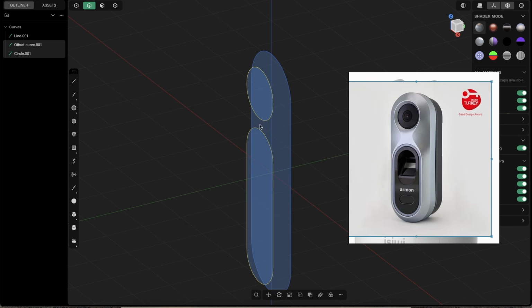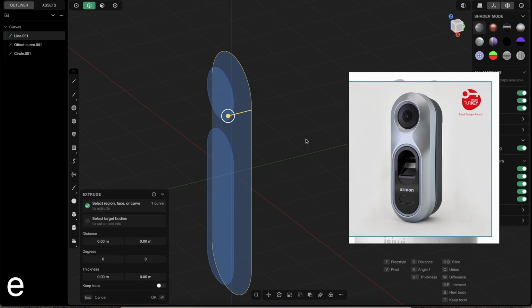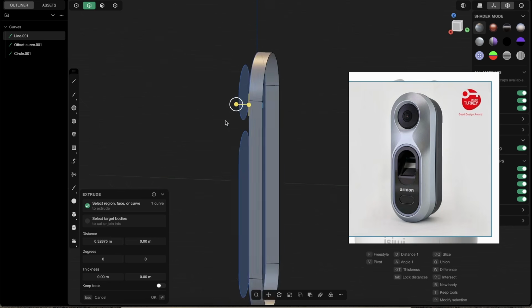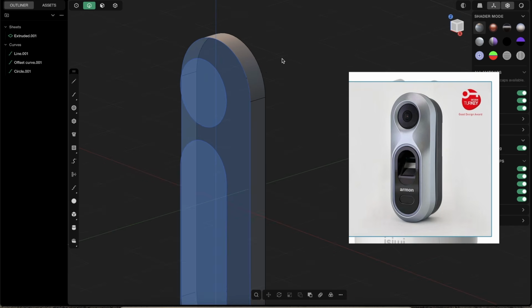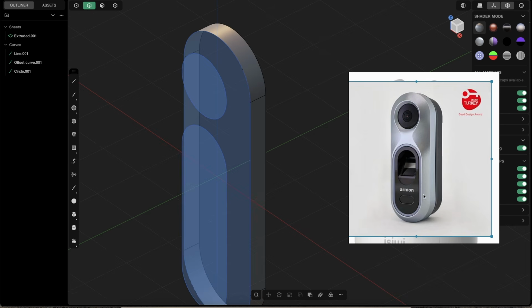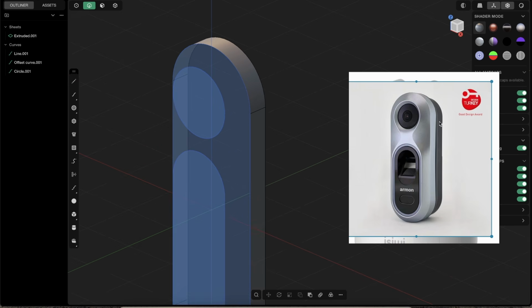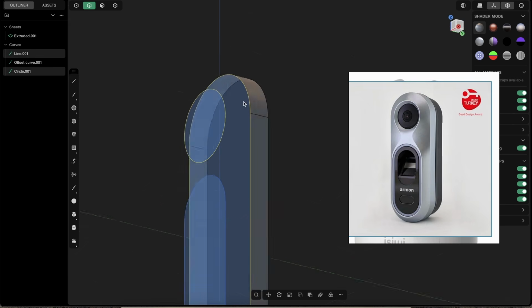And now let's just extrude this a little bit back. So select this curve, press E for extrude, and you can just extrude this and create here this nice little surface like that. And now what we want to do is create this whole surface which goes around. So basically this surface in the middle. And because you see it also always looks the same, it's very, very simple. We know that this surface will connect to our circle here, right? So it will connect those two curves.